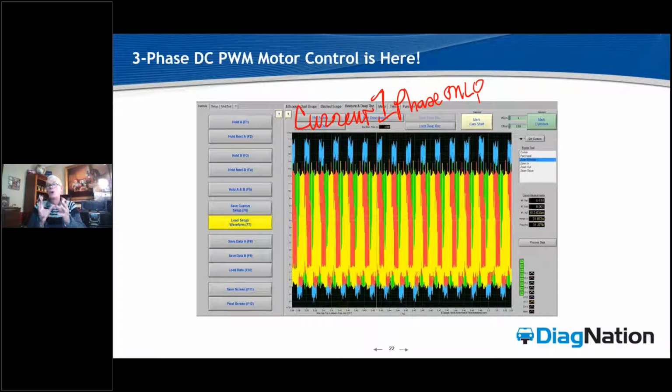But when we're testing motors, we want our voltage, which is your green, yellow, red here, as well as your current clamp around all three phases. Okay. And then you can diagnose one phase at a time to see which one's out. But for the purpose of this class, I didn't want to have three phases because that just makes the whole screen just one color and you can't really show anything.